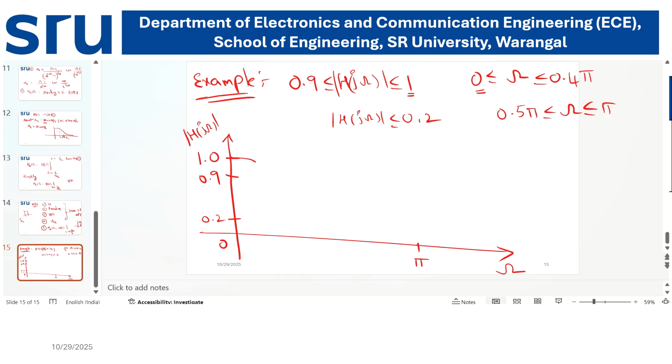Now we know the characteristics of the low pass filter. If I draw a line at 0.9 touching the characteristics, there we have one frequency, and where 0.2 touches, we have one more frequency. The point where 0.9 on the y-axis touches the curve is the passband frequency.